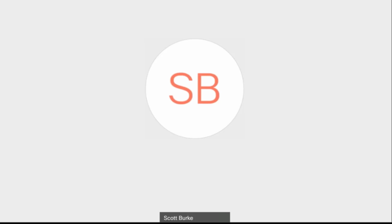So open the file, save it locally, change the name of the file up in the cloud, and then upload, recreate the shared file in the cloud, like create a brand new shared model. So you'll lose the previous restores for that one, but you'll still see the previous restores in the other file. So just give it a slightly different name and you'll still have access to all your previous saves as central. In that case, you want to take that drawing, maybe put it in a different folder or give it a date timestamp.